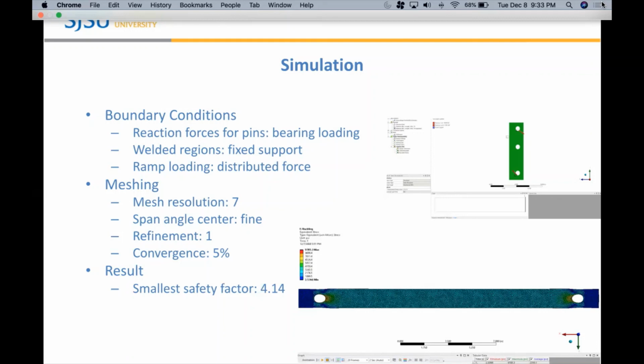Based on this, the simulation indicated that the part with the smallest safety factor were going to be the walls that were holding the ramp in place. The maximum stress was determined to be 9,660 psi, while the filler rod that we are planning on using had a yield strength of only 40,000 psi, resulting in a safety factor of 4.14. Based on these results, the motorcycle lift that we designed is safe to be used as long as the specified weight is kept in mind.